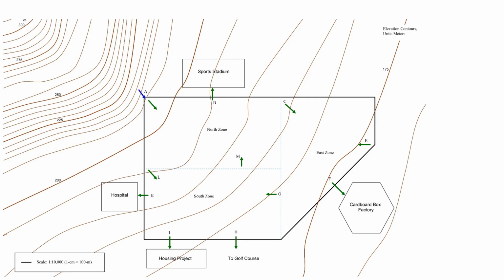This is a sneak preview of a map that you'll become very well acquainted with when we do the design project. In the design project, you're going to go through the process of looking at an area that's going to be developed and doing a demand analysis to figure out, based on a certain number of people in that area and knowing a little bit about how much water they'll be using on a per person basis, you'll try to size the pipes to figure out what's the most efficient route for the pipes to take, and also how big the pipes need to be in order to deliver a certain amount of pressure. What do you suppose these curved lines are? Contour lines. Elevation contour lines, that's right.